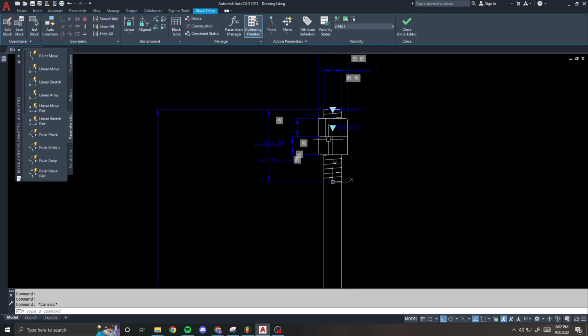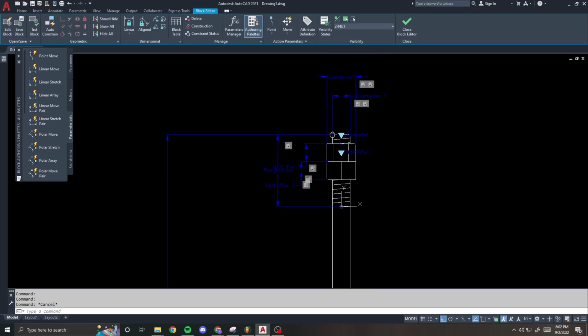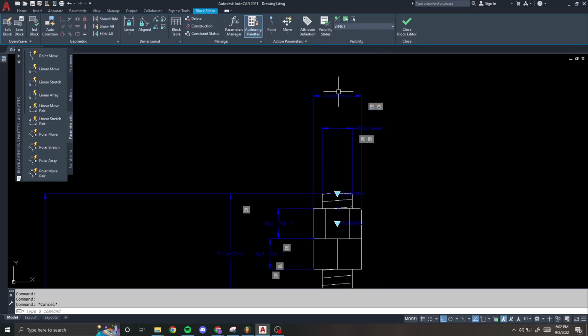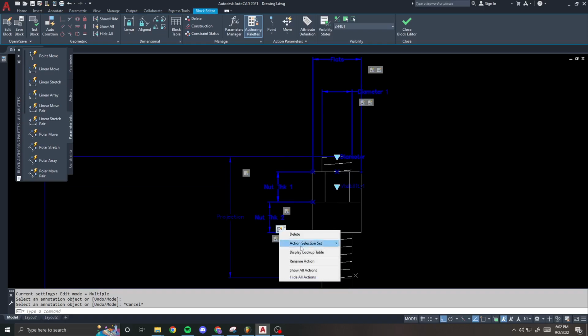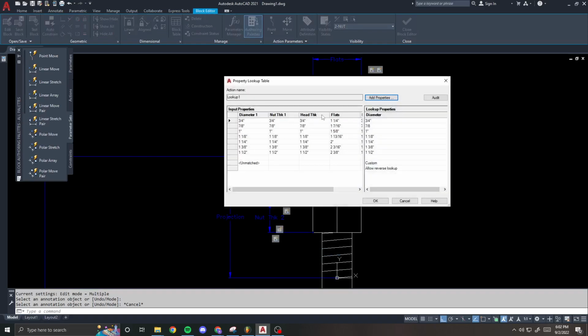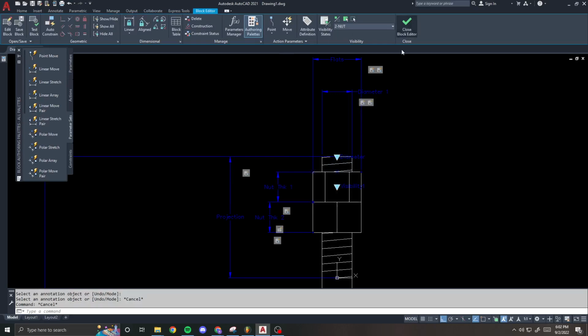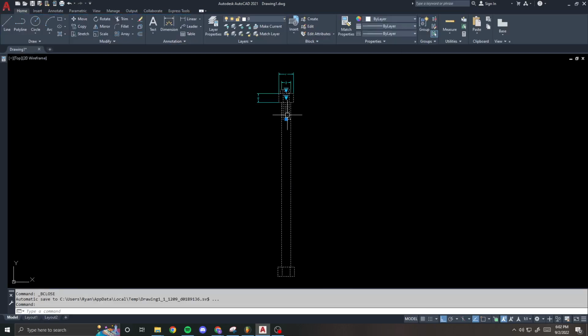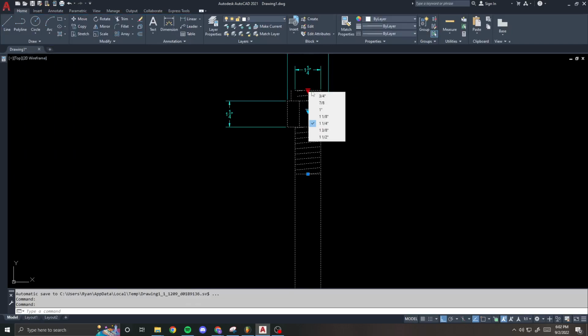All right, perfect. I think we're done. We can go ahead and rename this to flats. That way, when you look at your lookup table, it says flats. So that looks good. I like that. I believe you can rearrange these. Yeah, I just put flats at the end. All right, close, save. We now have a 1 nut and a 2 nut, right?